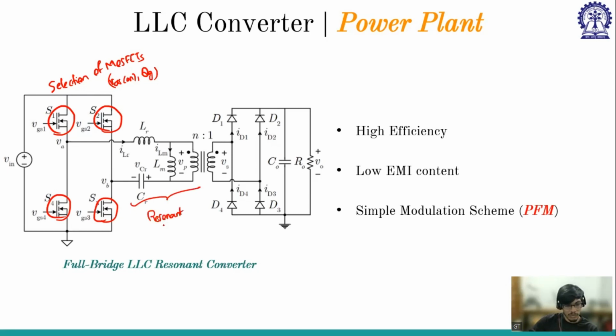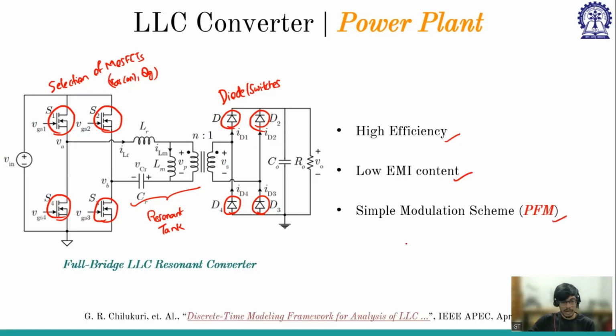What is the size of Lr? What is the size of the transformer? And here you can use either diodes or switches. These are some challenges in the power stage design, but we are not discussing LLC in detail. Our main intention is to discuss the use of a microcontroller in such a practical converter application. LLC is used because it has high efficiency as well as low EMI content, and it uses simple modulation schemes like PFM.